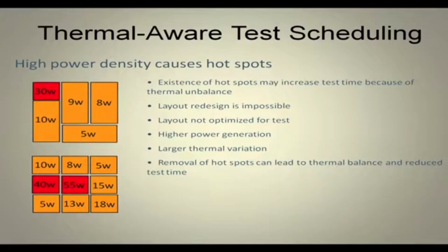So what will be required is that in the entire test session we need to put some gaps. We need to put some time gaps at which these paths, the routers and cores, will get cooled down, and only after that can we continue with the testing process. The introduction of these gaps, or idle times, in the test session gives rise to an increase in the test time.